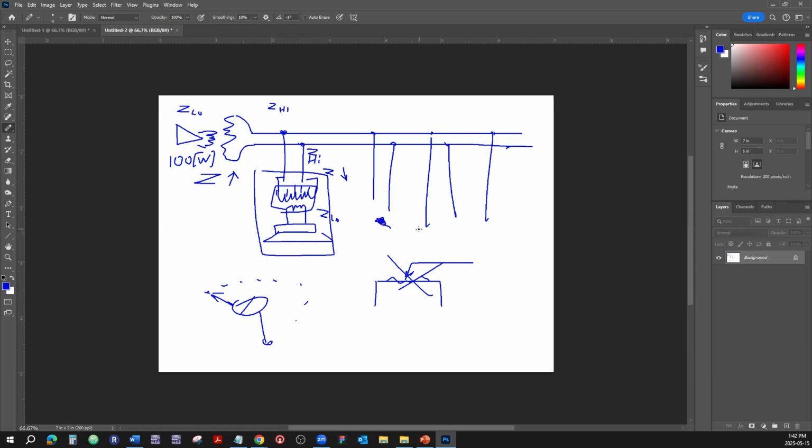But if you want to use a volume control, then let's say there's one more speaker here and here. The volume control will have the terminals that are labeled as input, and they also have terminals that are labeled as output. You just connect them, and the output is going again to the speaker station. That's how things are worked out. You can just put that volume control right in line with that. And this way you can just adjust the volume on the one particular speaker without affecting anything else. Well, you're changing the impedances, so it's going to affect a little bit, but not enough to be significant.